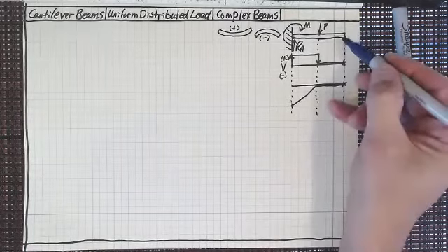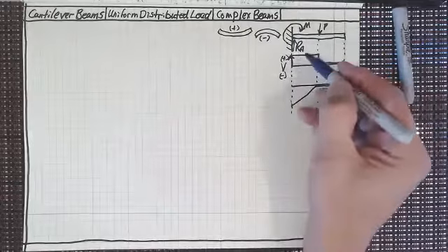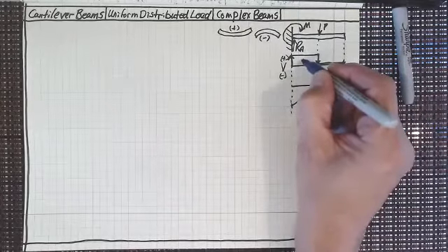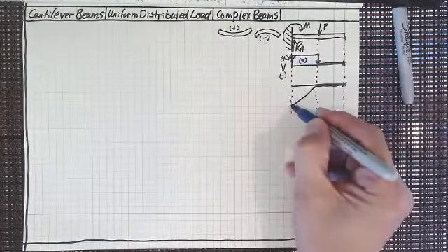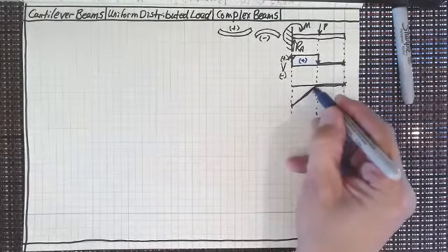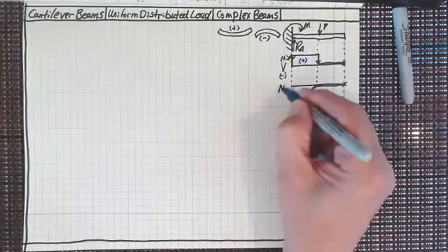And I realized that, no, of course not. That's not right, because this is a positive slope, right? It's positive. How do I know that? Because this slope here is positive, isn't it, for my bending moment diagram?